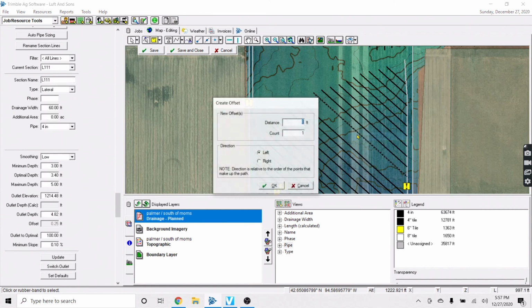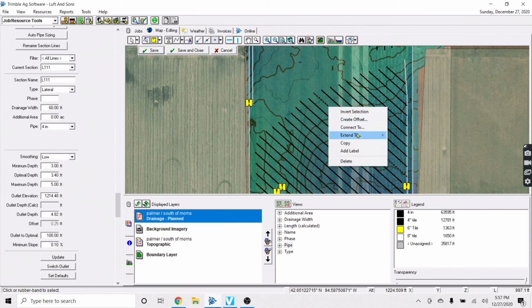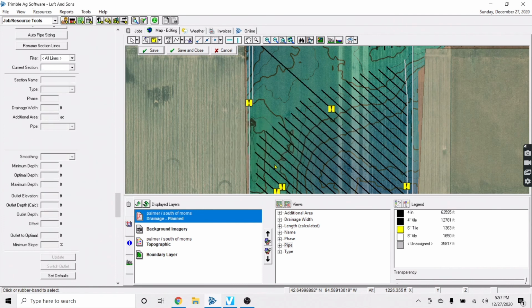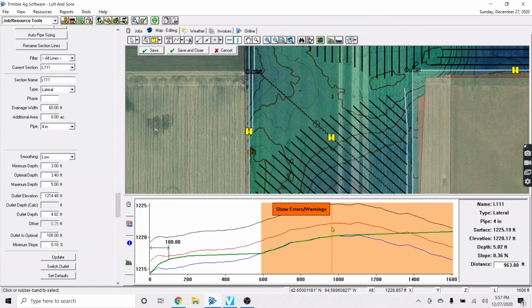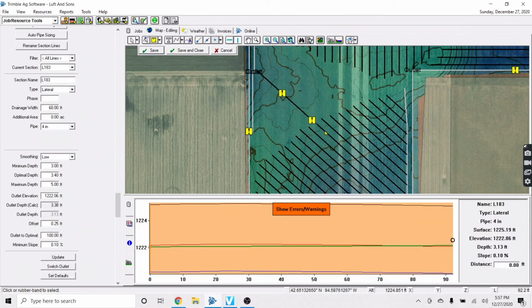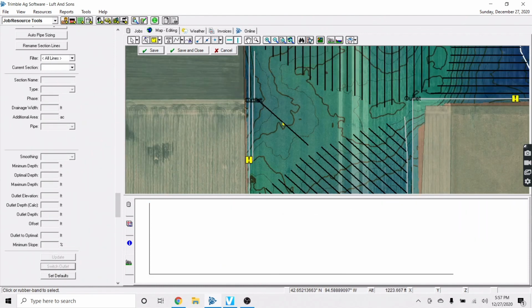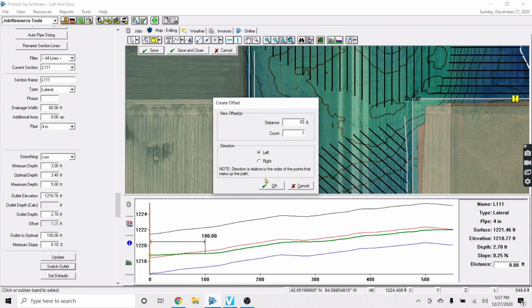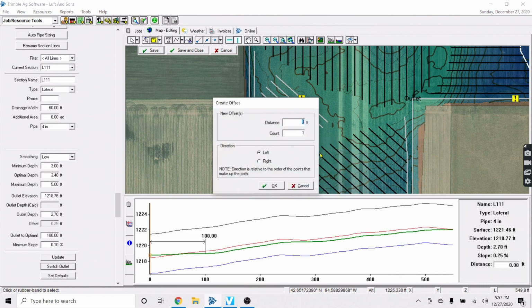Oh, what just happened to that line? It completely disappeared. So. Okay, send this one to the boundary. There we go. Now we're going to go into this view, go here where we had it, chop it off, click on this piece here, chop a little off so there's a gap in there in the top, delete the gap, click on the line, switch your outlet, so it's running downhill. Now we're connected down there.